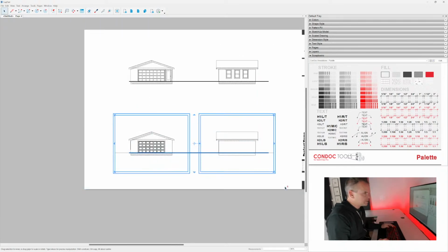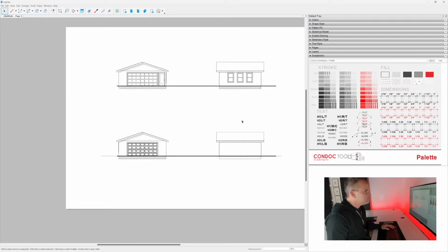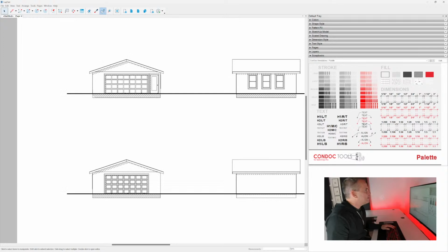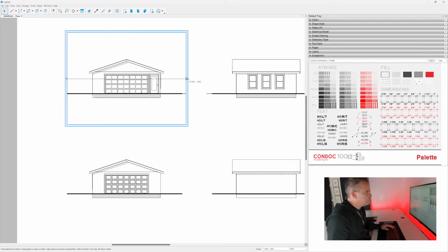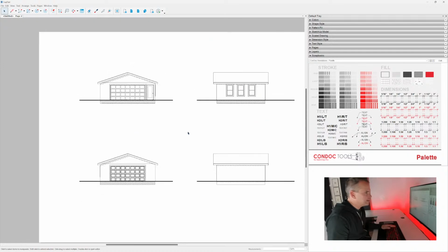And then maybe I'll just shift nudge. Shift nudge goes at like 1/4 of an inch. Let me stretch these out too, just to cover up those lines. And then I would use the slice tool, and maybe I would break between them, hover, and then bam, and hover to get my inference, bam, use my eraser tool to get rid of those. And then these viewports, I can just snap them to that line like that.